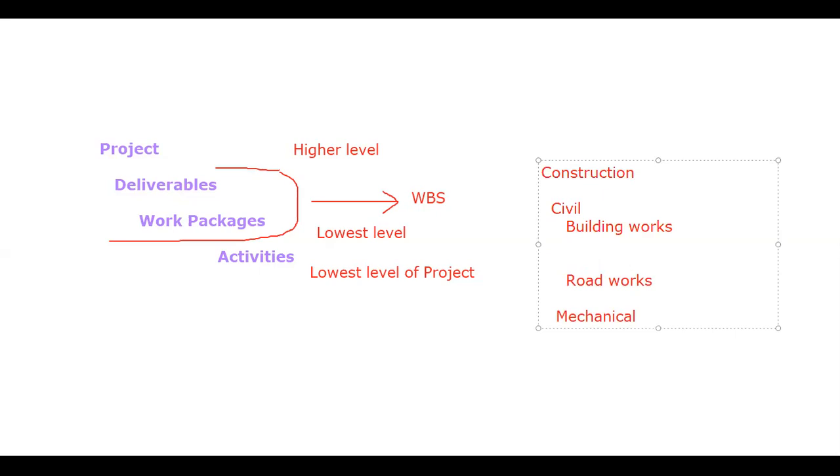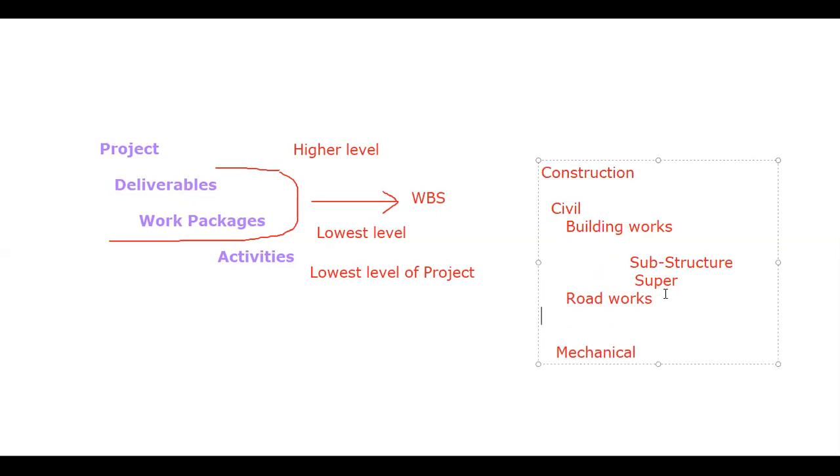Building works will be further divided into substructure and superstructure. The same way I can divide road work into earthwork, sub base works, asphalt work, and road furniture work. So the way I divide each and everything, I'm giving more detail about my project.